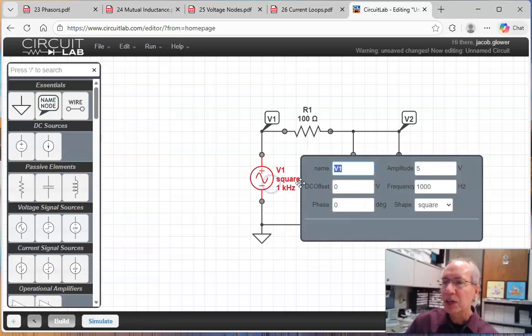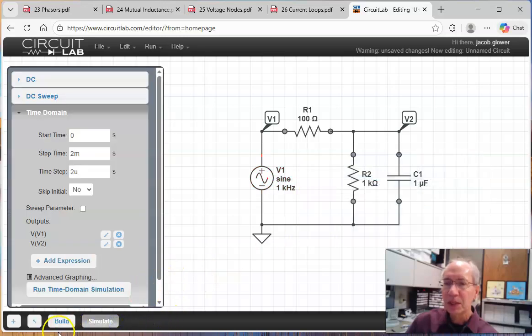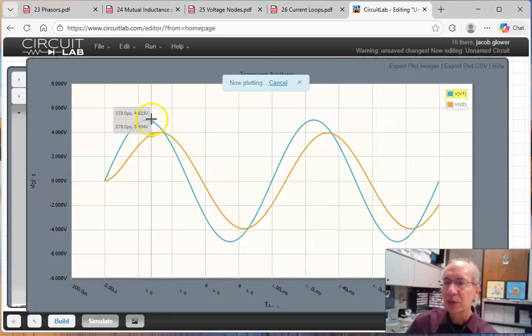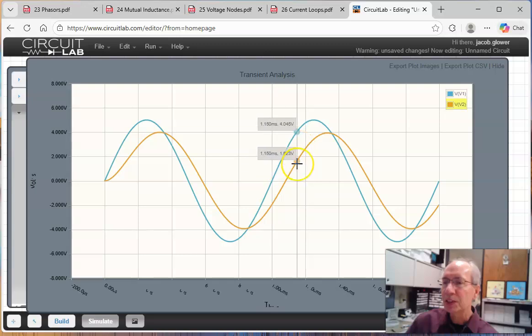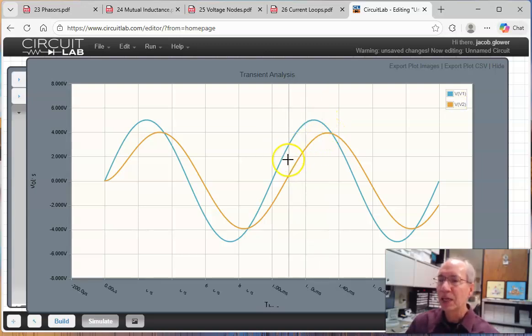Well, sine waves are eigenfunctions. With a sine wave, if the input is a sine wave, the output is a sine wave. Sine wave in, sine wave out. The difference is a change in amplitude and a phase shift. That's where polar or complex numbers come into play. I can represent that with complex numbers. I have an amplitude and an angle. That's polar form. I've also output a sine wave, meaning it has sine and cosine terms. That's rectangular form.